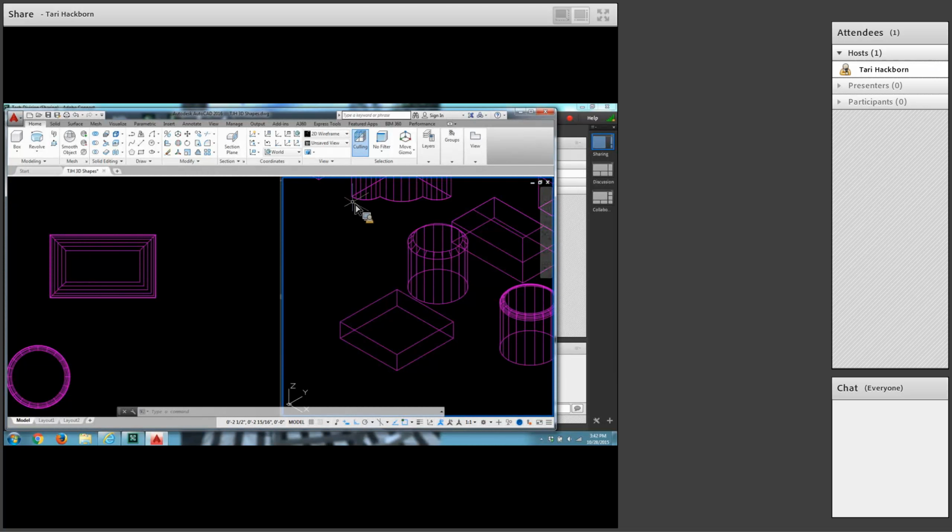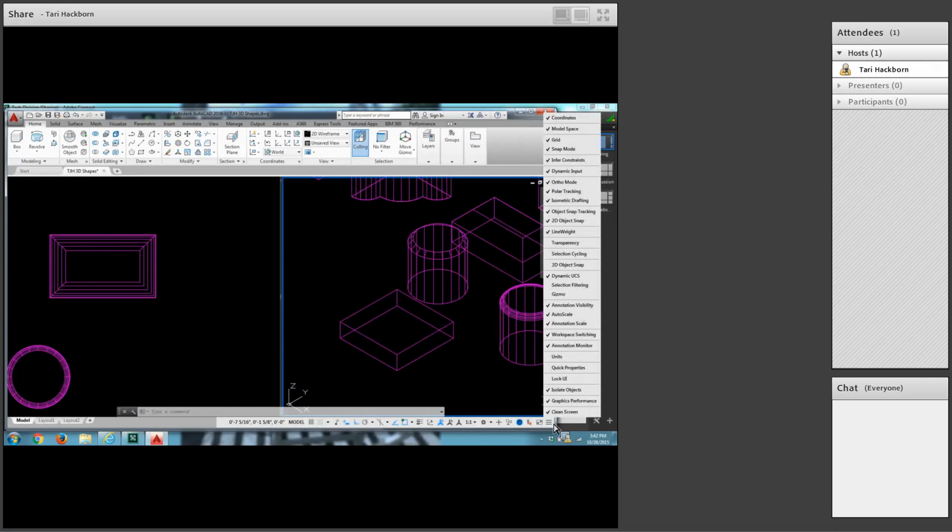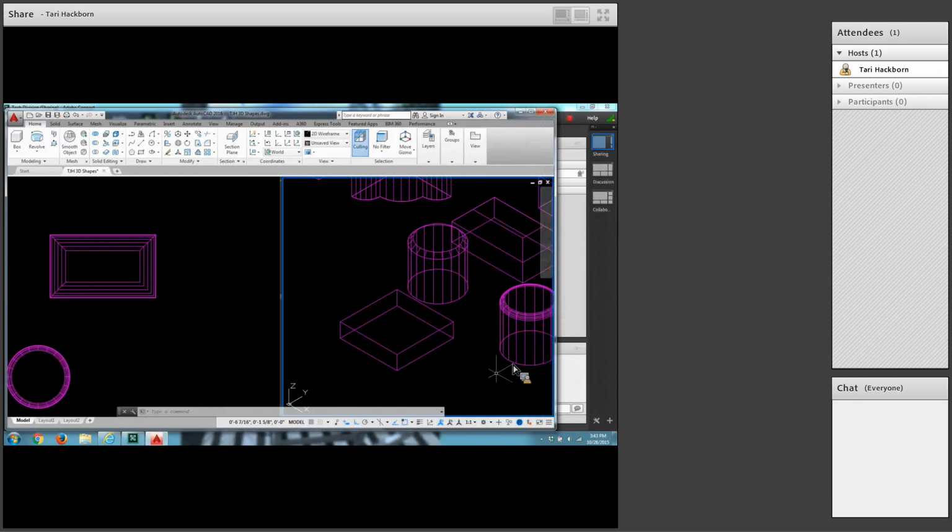This is the step on 63 where they want you to type cylinder, decimal X, and snap the midpoint of the front and the midpoint of the side and stuff. This will not work if dynamic UCS is turned on. So that means you're going to have to come over here to the hamburger and click dynamic UCS. And then down here, right here in your status bar, you're going to have to make sure it's turned off. Otherwise, it's just not going to work. Okay. The default is that it's turned on and it's running in the background, and for this, we need it off. It can be handy, but not for this command.